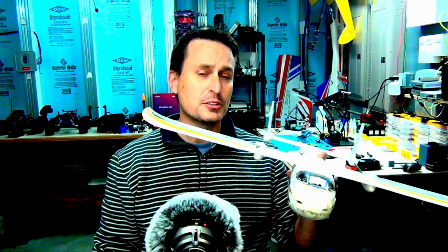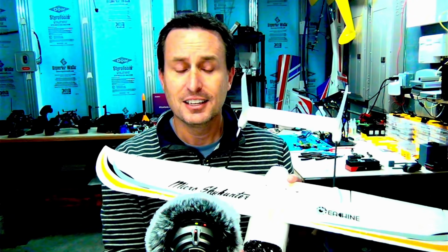And I think that's really what you'd be looking for. Why would you use BetaFlight on something? I wouldn't necessarily be interested in flashing BetaFlight to a wing that I want to use for long distance. I think iNav's the best candidate for that by far because it has return to home and all kinds of stuff. But if it's something fast and agile, BetaFlight has a lot to offer in this new release with how it adjusts TPA and PID.